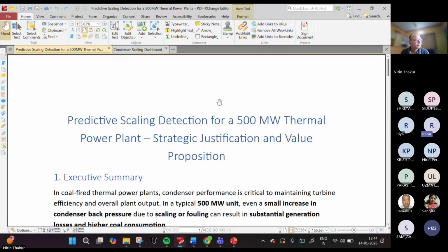Yeah. And the second thought coming to my mind is, can we put in any treatment package, because we are only talking of corrosion. So rather than working directly on the condenser, before that we can put a water treatment package so we can reduce the corrosion inside the condenser. That is the other way. Correct. Again, it's an additional cost. But that way we can improve the efficiency, I mean, coal consumption.